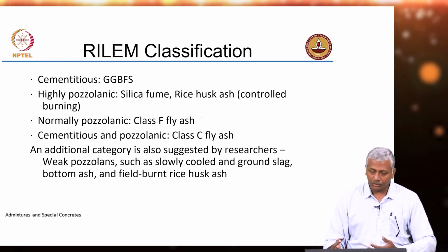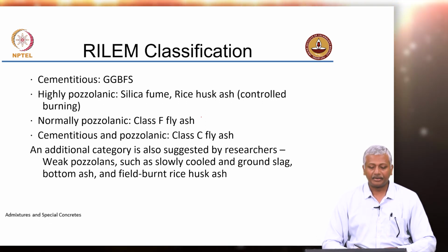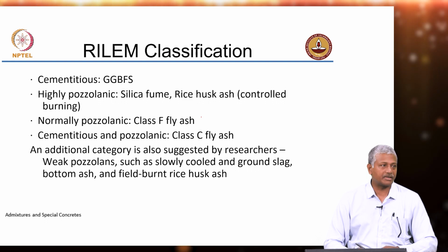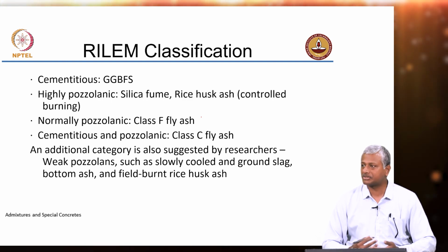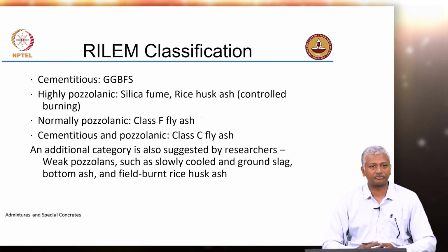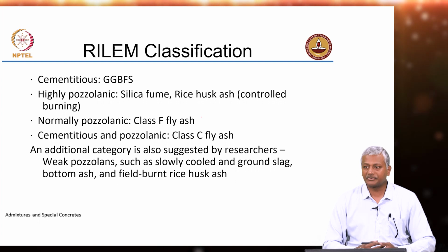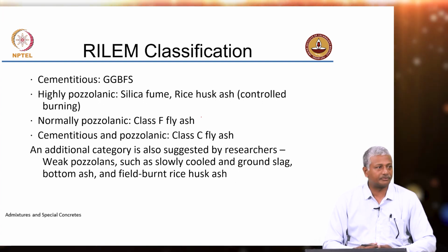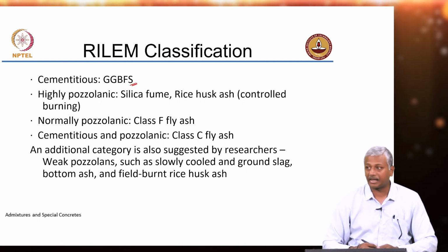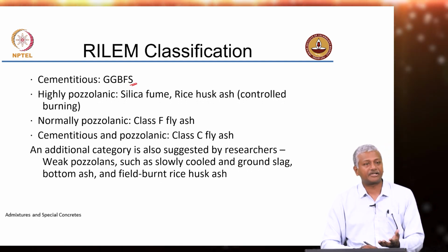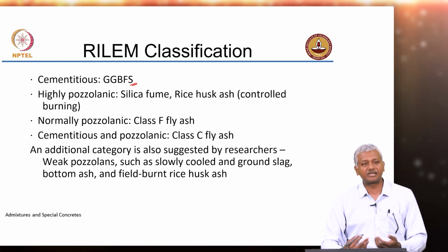Now, to classify these systems based on their reactivity, RILEM, which is an international organization which looks at the research and industrial application of various types of concrete materials, describes the mineral additives or supplementary materials as cementitious when you have, let us say, slag, because slag does not need calcium hydroxide, as we will discuss later. It can react on its own with water with some activation.